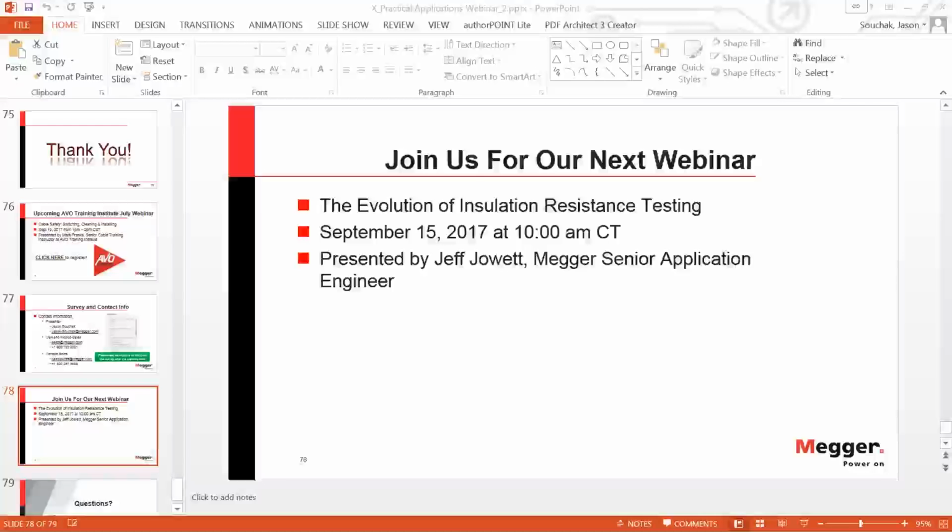All right, thank you, Jason. Next question is for Henning. If the cable is long, the capacitance increases. Here, according to you, VLF can't be used. Then what should I do? Well, you cannot say VLF cannot be used. The best way to approach this problem is to do a quick calculation of the cable capacitance, and then compare that number to the test capability of your test equipment.